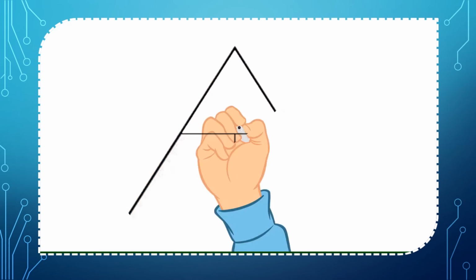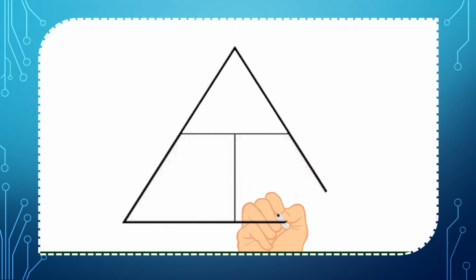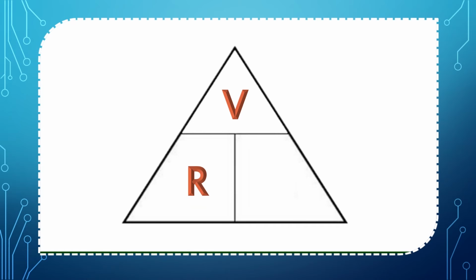I've asked Professor Jim to draw the Ohm's Law Triangle for me. He's really fast. Thanks, Professor Jim. I'm going to add the symbols for our formula, V, R, and I. Then you will see me substitute them for the actual values. The voltage is 1.5 volts. The resistance is unknown, and the current we just measured is 1.5 milliamps, or 0.0015 amps.